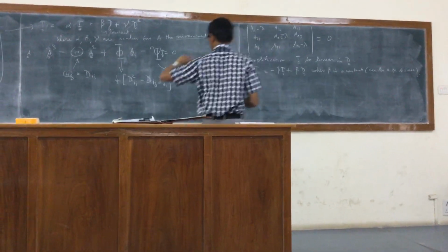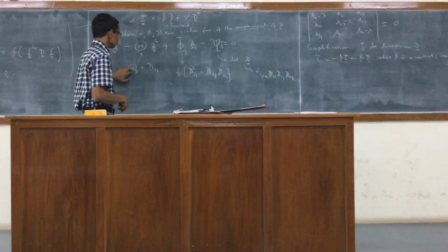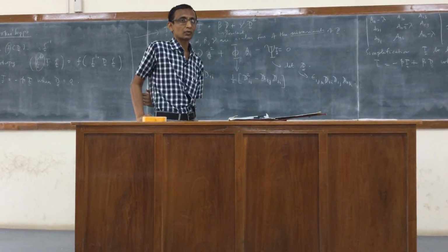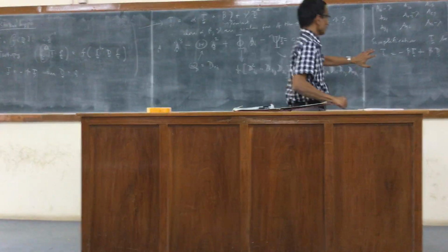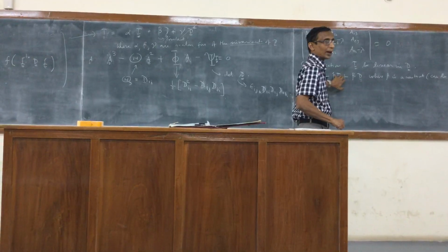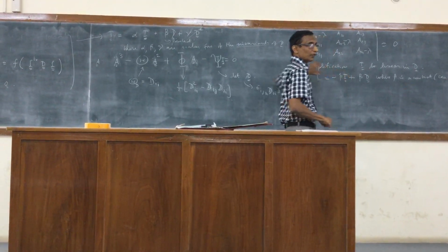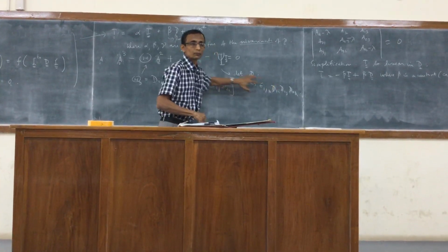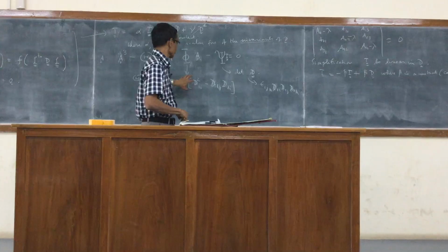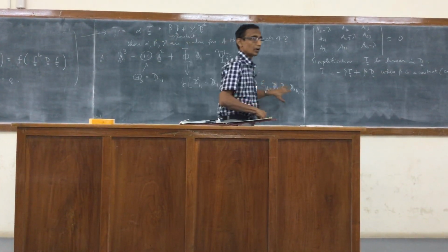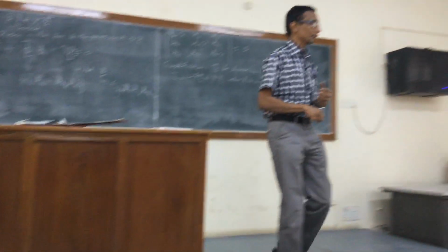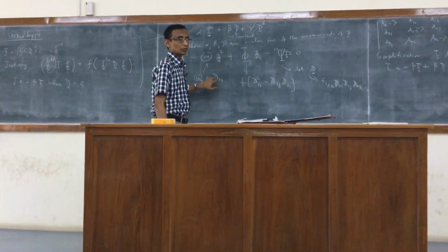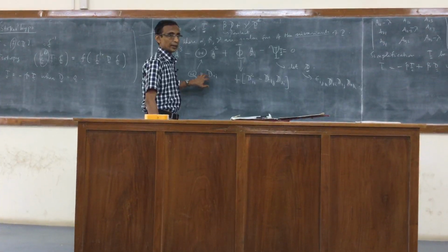But if you now look at the invariants, this is not the most general form, because whatever comes here will be multiplied only by I, right? So now if T is to linearly depend on D, certainly these are ruled out. The alpha cannot be a function of the second and third invariant, but however, this is linearly related to the elements of D.